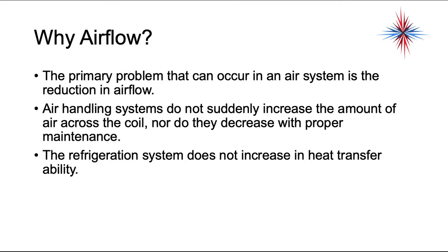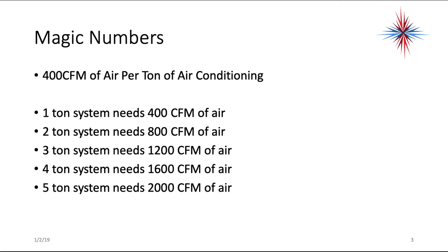We want to make sure we don't have a reduction in airflow, and we want to make sure we don't have too much airflow. Air handling systems do not suddenly increase the amount of air across the coil, nor do they decrease with proper maintenance. A refrigeration system does not increase heat transferability based on airflow. It's going to have the ability to remove the same amount of heat, but the airflow makes a tremendous difference in the comfort and the efficiency of a unit, and we'll talk more about that as we go further. There's some magic numbers we want to make sure everyone's aware of before we delve into this.